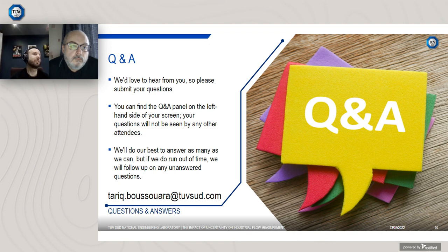If you can get access to the internal surfaces, you can do dimensional measurement. So in the past, we've sent things away to be dimensionally measured with very high accuracy. One thing we actually did was, for a particular project, we sent the component away to be digitally scanned. So a high resolution mesh scan was developed of the model in its basically uneroded state. We then subjected it to erosion, rescanned it, and then you can overlay the two 3D meshes on top of each other, and that produces a really high accuracy map of erosion.